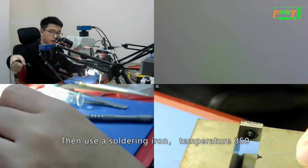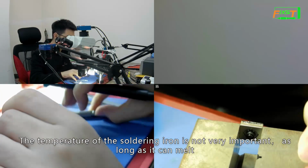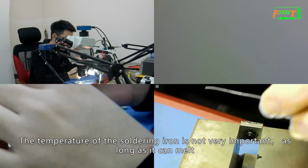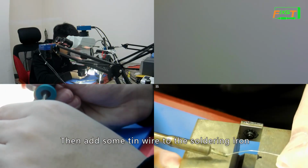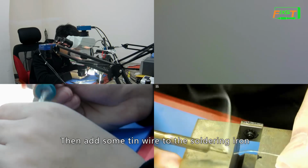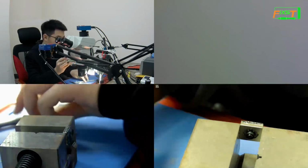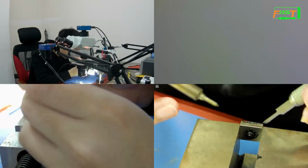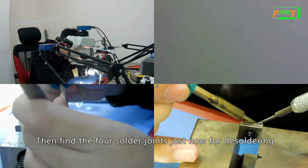Then use a soldering iron, temperature 350. The temperature of the soldering iron is not very important, as long as it can melt. Then add some thin wire to the soldering iron. Then find the 4 soldering joints just now for desoldering.